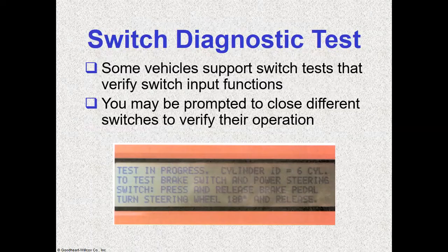Especially with modern vehicles that have a module for the lighting system and the wipers, you can use the scan tool to operate the wiper blades, trigger the pump, and trigger the headlights. Anything that involves a switching function, you can use the scan tool to operate.